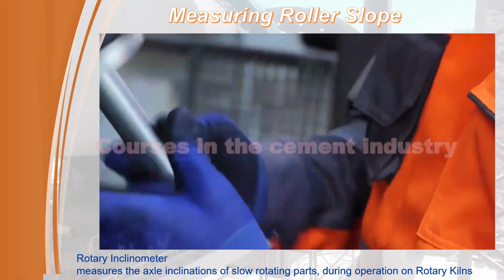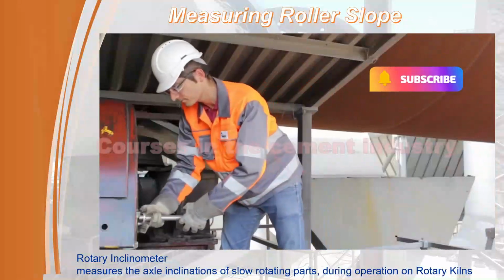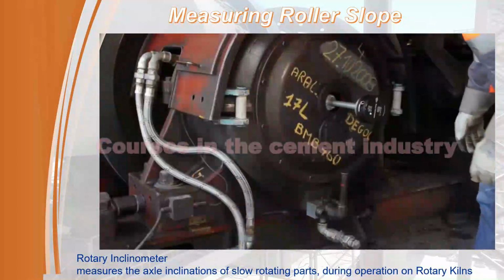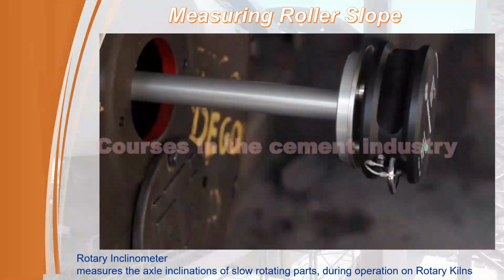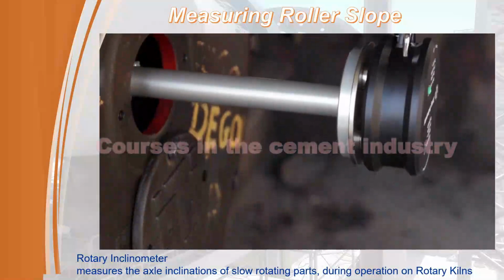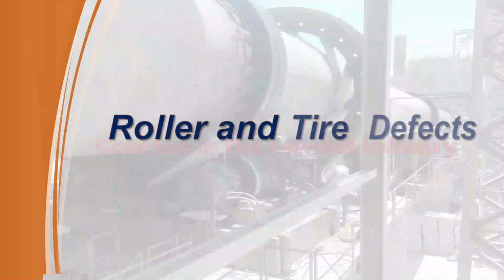Attach the rotary inclinometer to the shaft center adapter and fit it to the kiln roller shaft. The calibration basically consists of two normal inclination measurements, which are performed on the same rotating part but in different directions. That means, for example, like here on the support roller, once on the uphill side and once on the downhill side. Roller and tire defects.